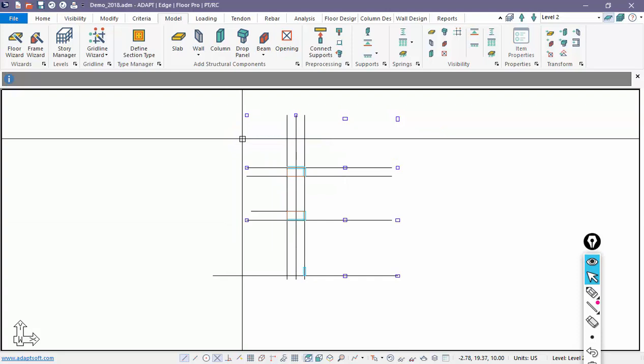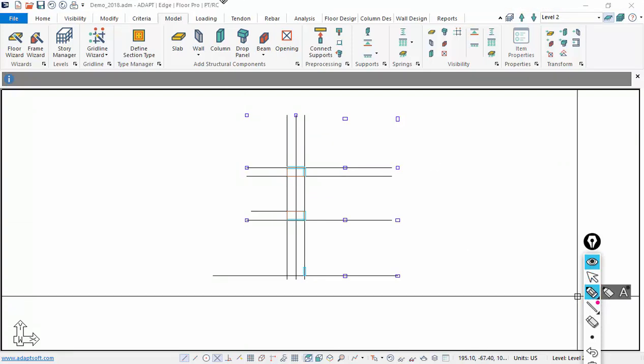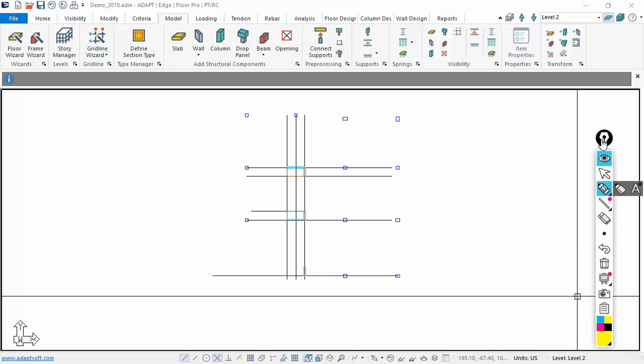In terms of the slab, let me go ahead and mark this. We're going to have a step here. This is like a 2-inch step down to the face of this column. And then we have a step here. This will be inward by 4 feet. It'll be at the face of the column.